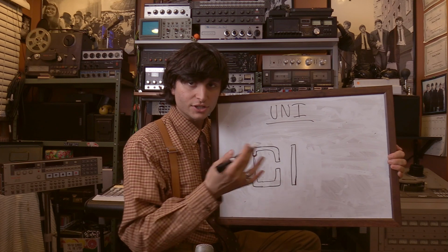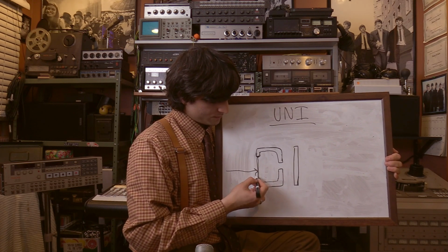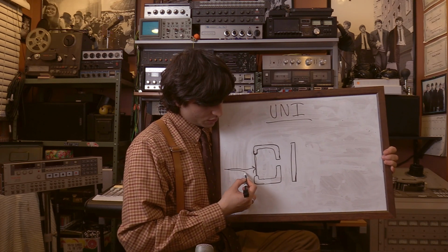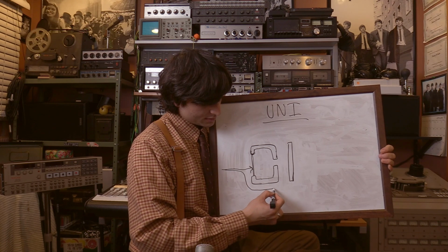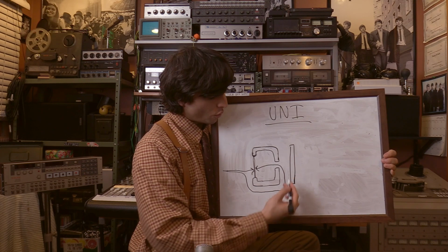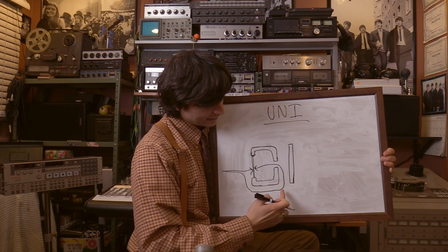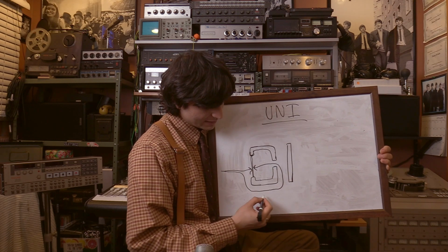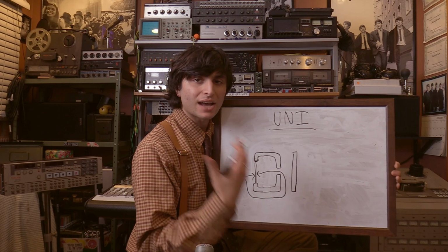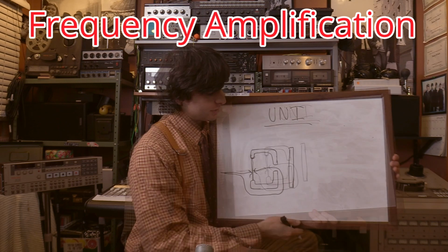So when a sound is coming from the front of the microphone, it is going to hit the diaphragm, causing the diaphragm to move. And it is also going to travel around and come through the rear port of the housing. And the specific length that the second path takes in relation to the first path is designed to amplify that sound frequency.